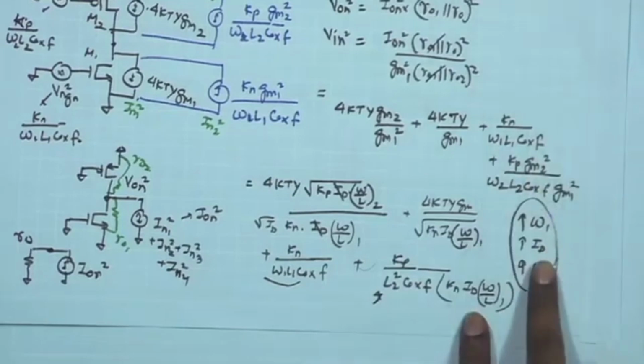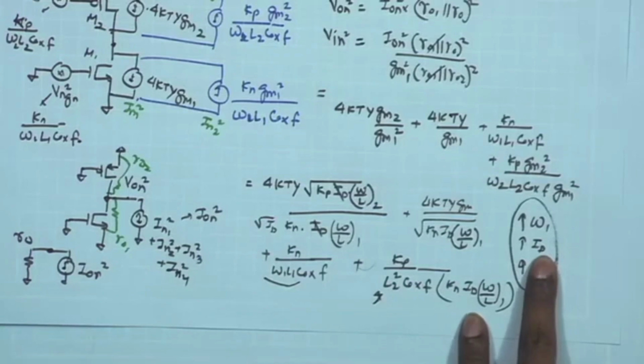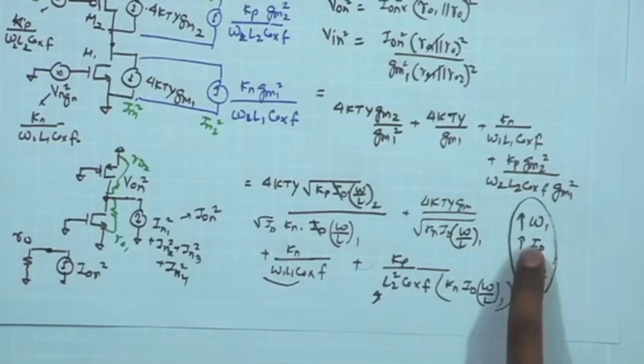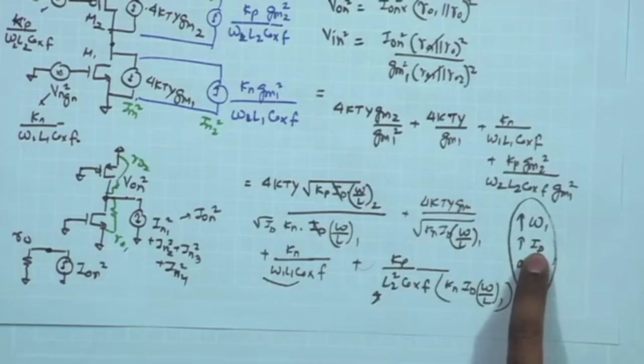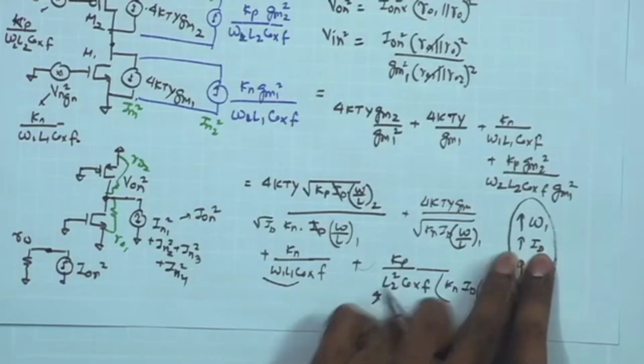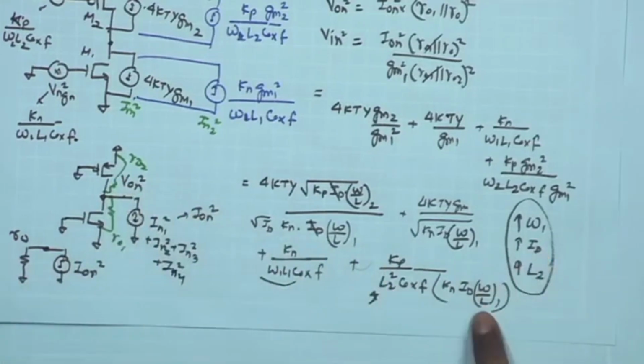So, we see the trade off with the bias current first of all, and in our case when we are having a low power application, we are talking about multiple channels, each of them having such a dedicated front end amplifier. Bias current is having severe constraint, and therefore, we just cannot go on increasing the bias current to cater to 1 upon F noise requirement.